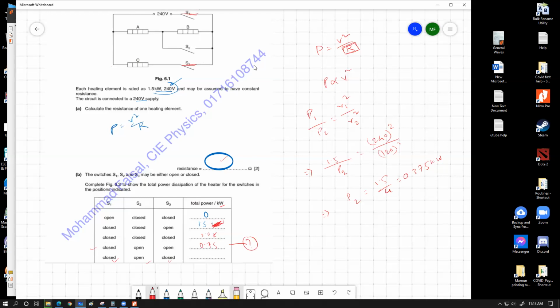So basically now the current can flow through these two branches, which would be in series, and the current will also flow through this whole thing. You have to see that these two combinations are in series, so they are going to be getting half the voltage of the supply, pretty much like what happened over here. Additional to their heating effect, we're also going to have some heating effect of this heating element C, which happens to be directly connected to the supply. You can have a look that current can directly come over here, and the current can directly get out of it here as well.